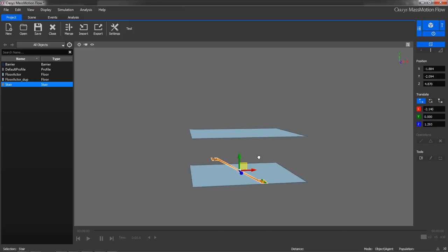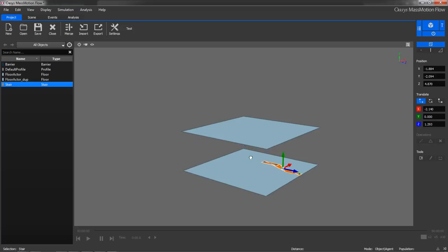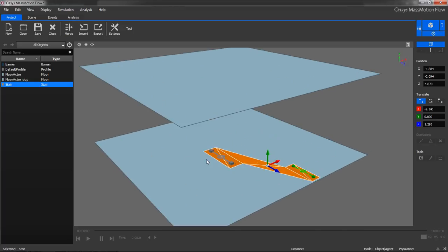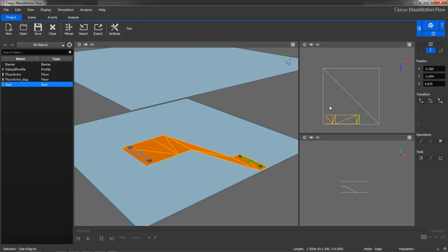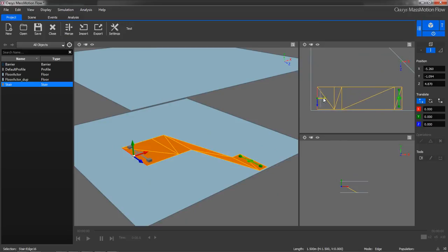And the floor-to-floor distance here is a bit high, and so what we'll do is we're actually going to use a bit of this stair to create the floor that we need at this level. So what I'm going to do is go to my edge select mode, and the key shortcut for that is E. And now I'm going to press G for grow, and I'm just going to adjust it like so. I'm even going to take a quick look at it here in the top view so that I can get my alignment with the exterior wall sorted out.